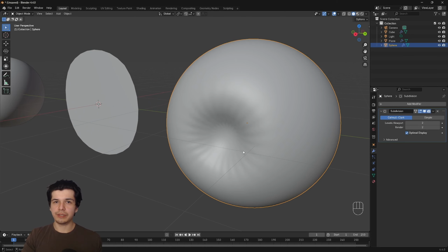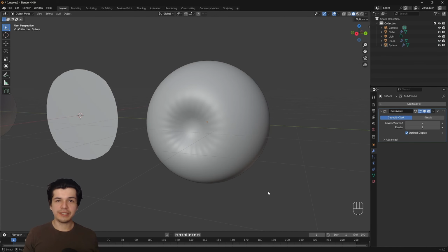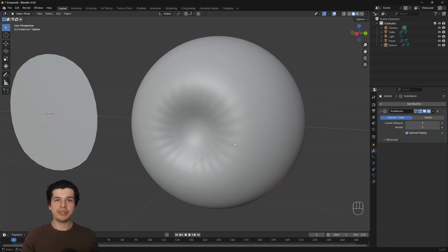It has issues with the surface and it doesn't look so good. And it is because the construction of this model is not properly made for the subdivision. So these triangles can cause issues, and there is an unspoken rule that you shouldn't be using triangles when you are constructing in subdivision.